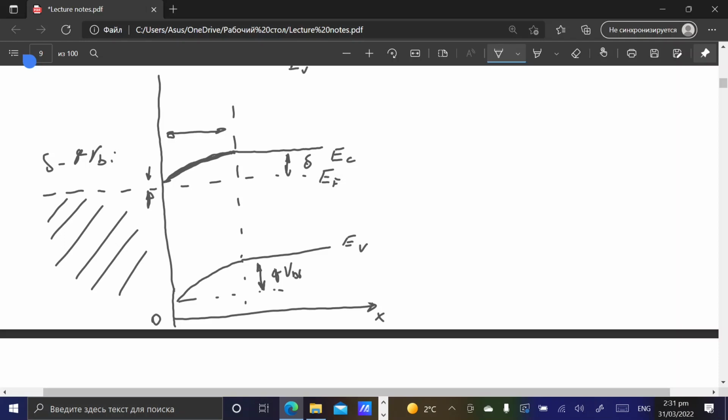So in this case, when we have N-type semiconductor and we want to create an ohmic contact, we want to find a metal which possesses work function smaller than the work function of the semiconductor. If we want to make a rectifying junction, Schottky junction, in the opposite, we need to find a metal with work function larger than the work function of the semiconductor. So in that case, these processes of charge transport change direction.